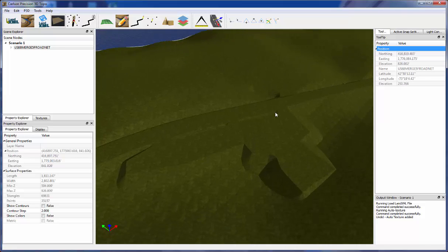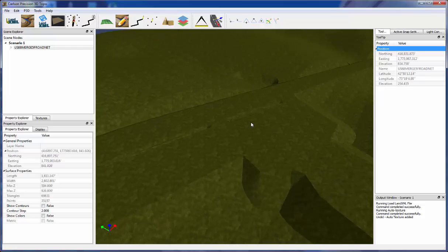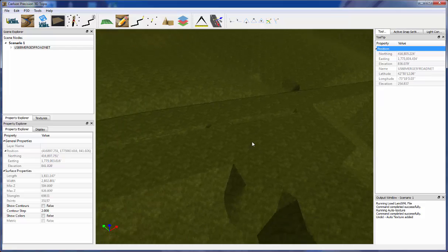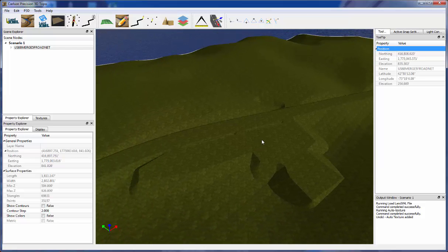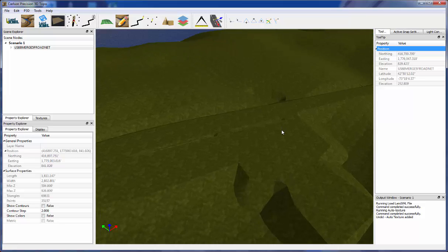And what we're going to do is texturize. We're going to use the auto texture. We're going to texturize and colorize and dress the system up. But we're also going to use those textures in this 3D environment to try to spot surface anomalies that would not work if you were to send this LandXML file out for machine control.